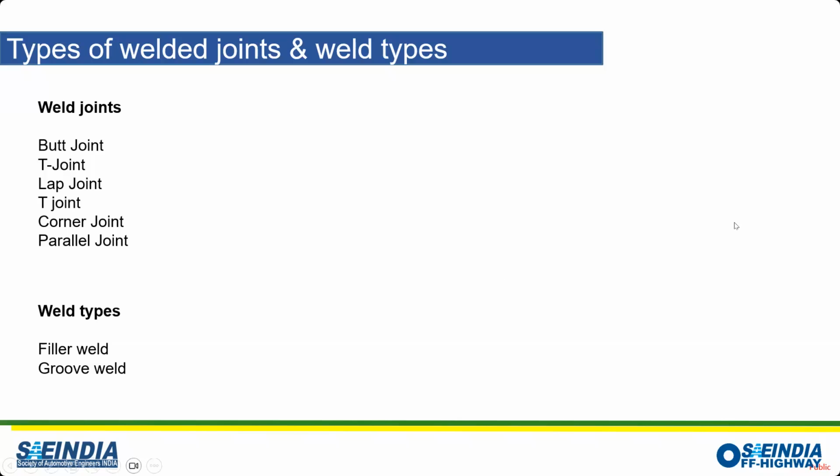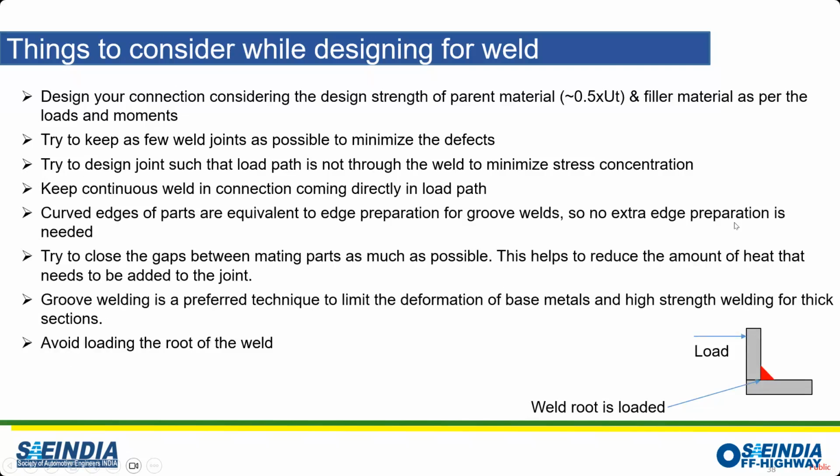I think we can move to the next slide here. Yeah. So while you're designing your structure, there are a couple of things you can consider while you are doing the calculations and choosing where to put the weld. While you're designing your connections, be very sure about what type of loading you're going to get on the part, and where the loads are going through, so that you're putting as little stress into the weld as possible.